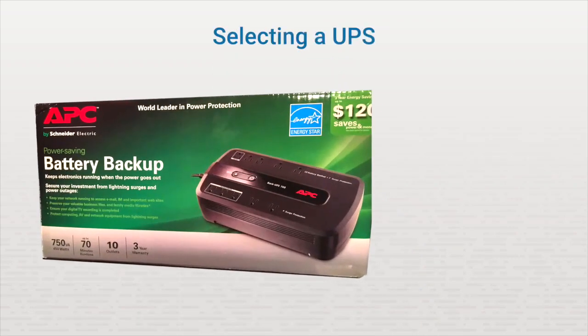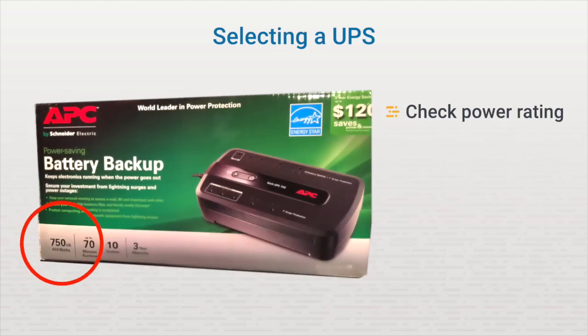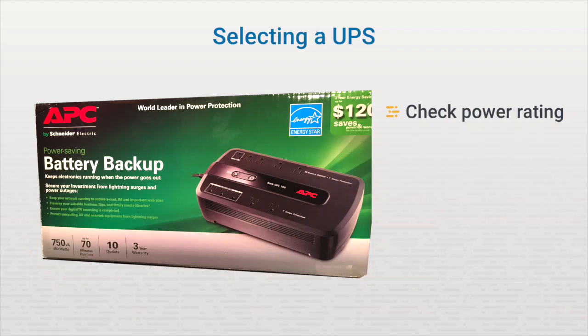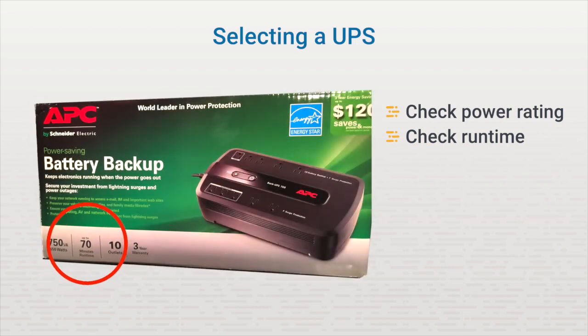You don't want the power to go down on a server. For workstations, many people use an offline UPS because they're less expensive, and if the system goes down, it isn't as painful. Use your organization's values to decide which type of UPS you need for each device. When you select a UPS, look at the battery power. Some UPS devices have larger batteries and can supply power for a longer period of time. Look on the box for a rating that says how long the battery will last. It'll say something like, this system will power one PC for 20 minutes.